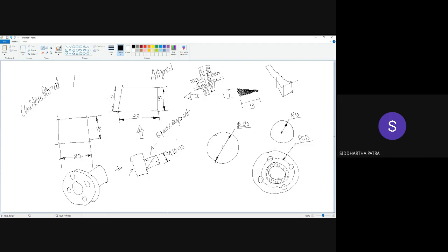Things like that you would only learn when you encounter such problems, and as of now I don't think a lot of things have to be learned about dimensioning, but do keep in mind a few of the things. One is the aligned and the unidirectional version of dimensioning, how you should put dimension for diameter and radius. Okay, and also the ratio of the width and length of the arrowhead. That should suffice for the moment.